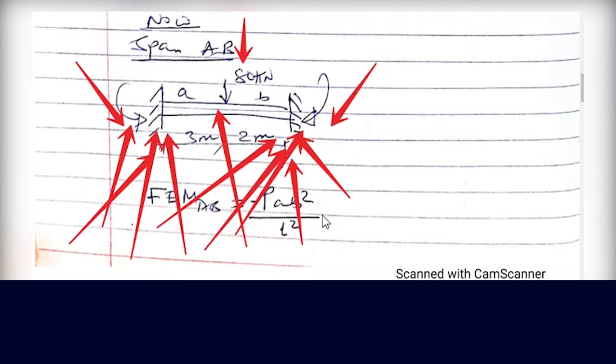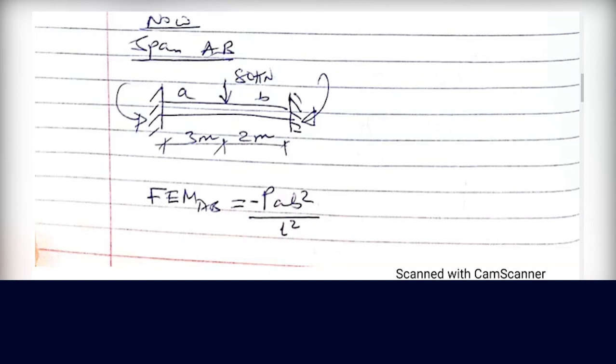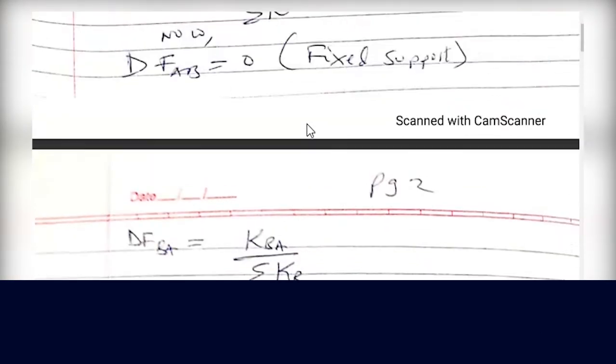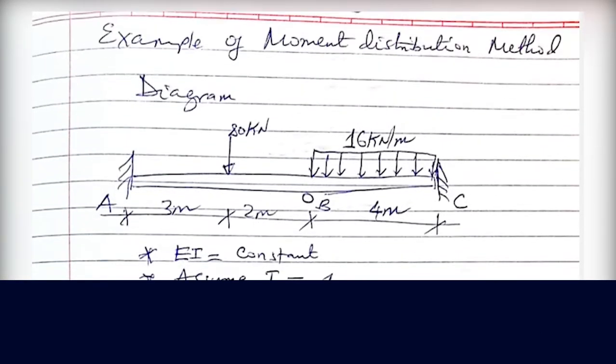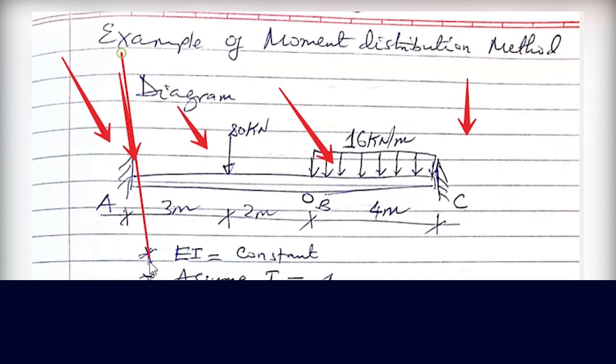So you can have your shear at this support, and hence you can draw the bending moment diagram and the shear force diagram, as in the general case given with the fixed end supports at these two points.